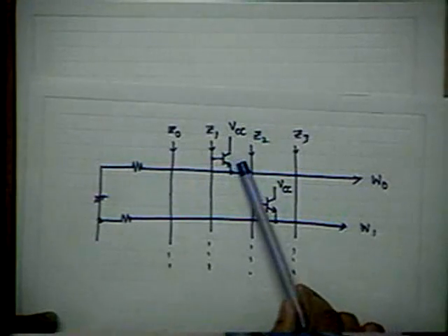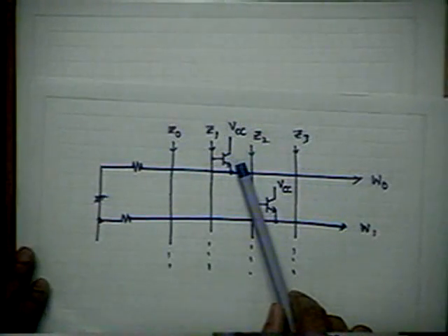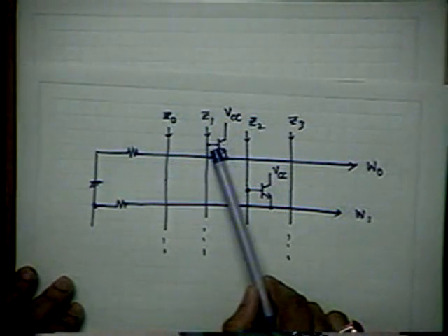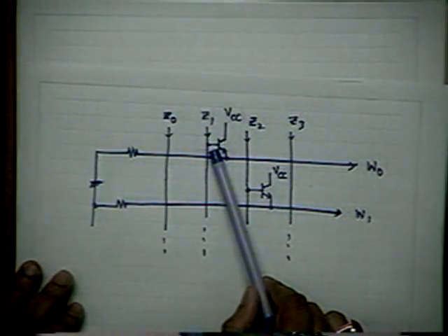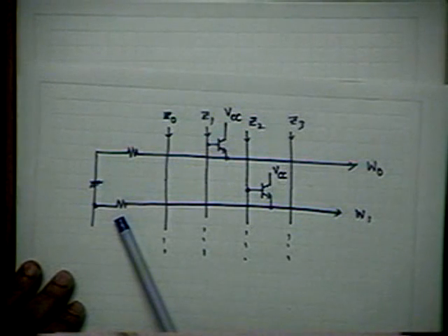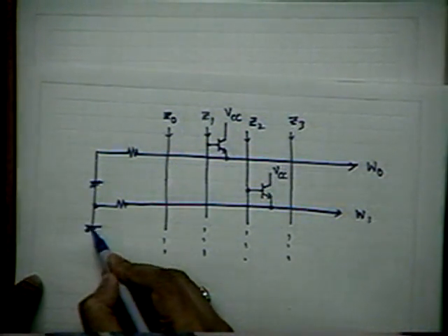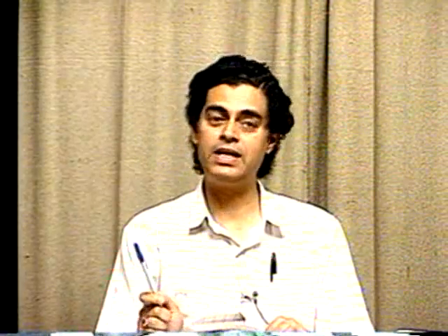But then, as you know, the MOS technology came. You can really replace these diodes, these transistors, by MOSFETs. You can put a MOSFET, but that is normally not done. What do we do? We never use resistors in MOS technology, because resistors unnecessarily occupy a lot of area. So we shall do exactly the same thing which we did in the realization of PLA.